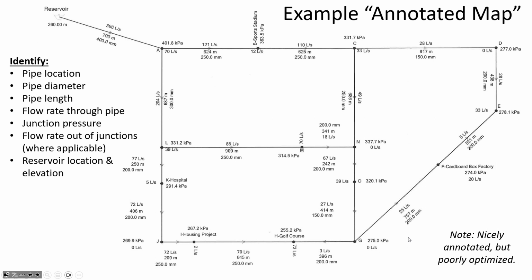So there's no reason for the pipe to be there, for the junction to be there. So an improvement would be having the water go straight from K to I. So a straight line would be less length, less cost. So part of your job is to optimize the pipe diameter, but it's also to find out how you could minimize the length while still getting to all of the locations that water needs to be delivered.